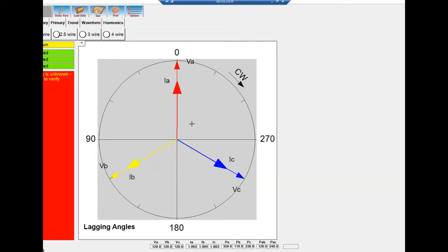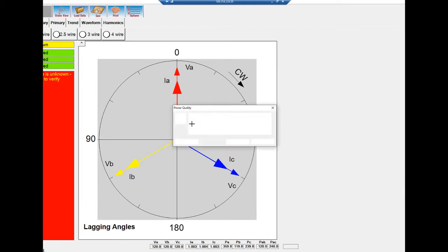So now we're going to go over a little bit more of the advanced parts of power quality, some things that might trip you up, as well as what you can do with harmonic content once you see it in power quality. One of the things that I've noticed out in the field, and one thing I've even done myself, is using a rope probe or a clamp probe, some form of primary probe, to measure current in the field in power quality. You can do that.